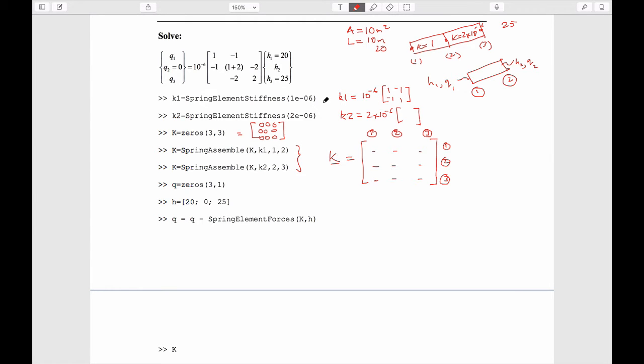And it wants to put these terms for location 1. I did it again, right? I should have bracketed this in our terminology. These are the global ones, which are bracketed. And it takes the indexes, 1, which is this term here, 2, which is this term here, and it knows exactly where it wants to put it. It puts it in these 4 slots. And that is what we called before element number Roman 1, which is this, versus Roman 2. And those are added in the right place.